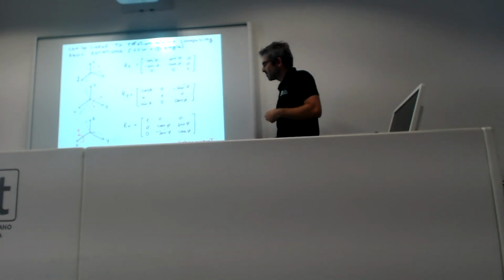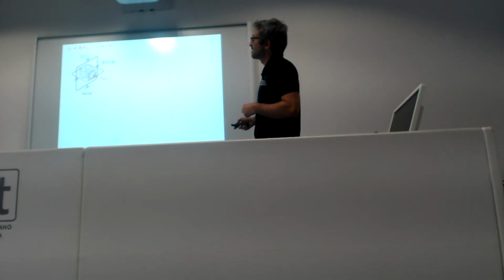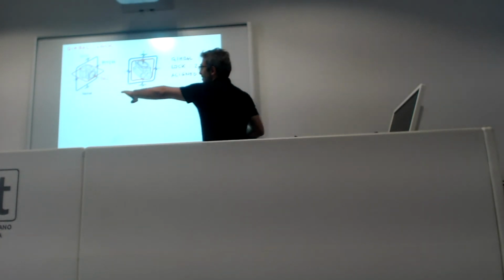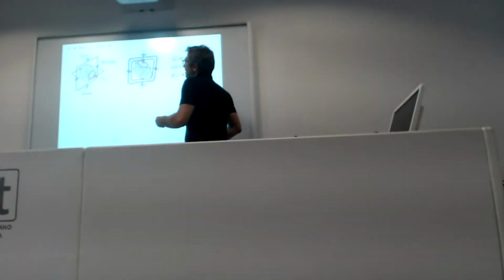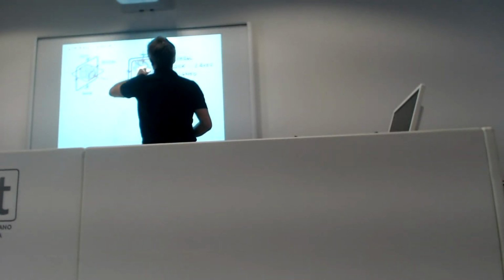And these are subsequent rotations. The gimbal lock happens, for example, when the pitch is 90 degrees, so think about this moving up 90 degrees, then you're not able to distinguish between yaw and roll.